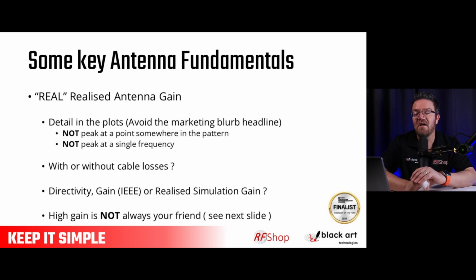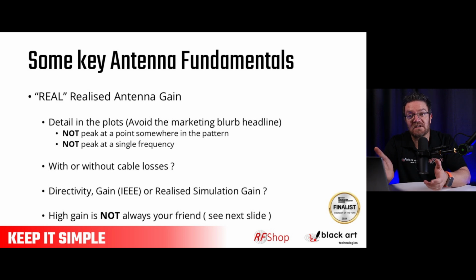And as an example, if you have a radiation pattern, it may say it is a 6 dBi omni antenna, but it happens to be more like 4 dBi. But somewhere in the pattern, if it's an omni antenna, it has a peak that hits 6. Then good, it's a 6 dBi omni. Not if you think that 6 is the whole band, then it's not true. So half-truths is a dangerous place to be. Also, if you have wideband antennas that are just single structures, like a single dipole with multiple resonators, and they say, well, it's a 6 dBi antenna from 700 megahertz up to 3.8 gig, just referring back to the 4G, 5G world.